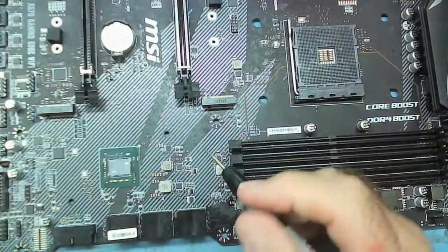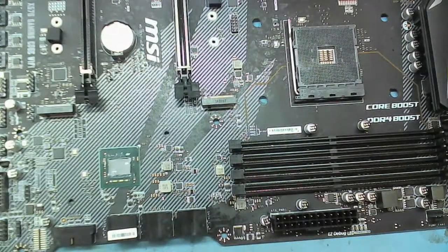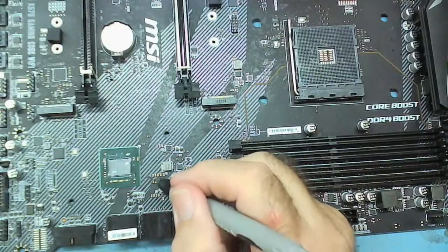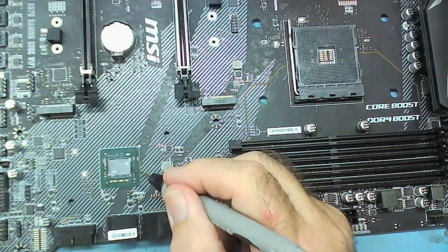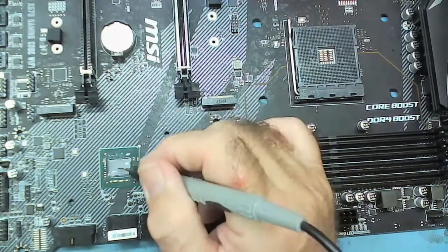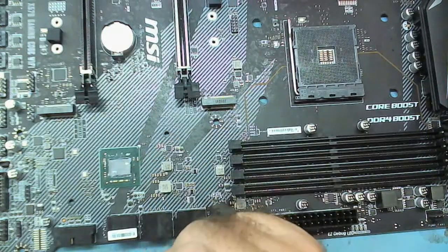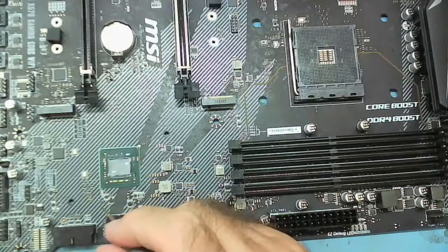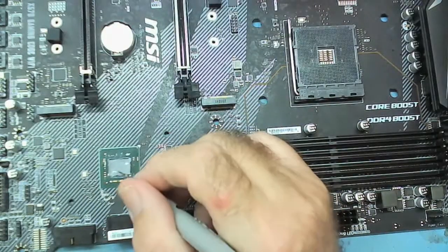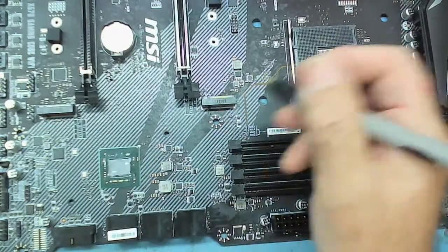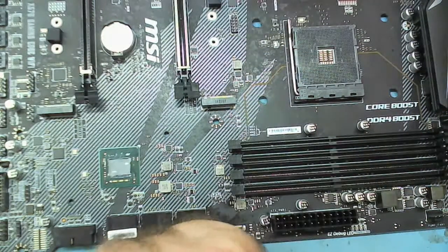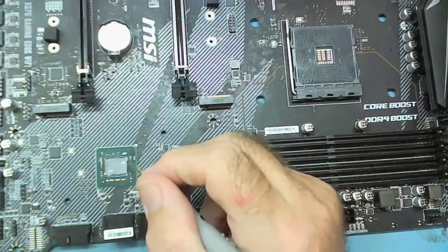So this is the board that doesn't power on, and we know as a fact that this North Bridge, or PCH, whatever you want to call it, platform control hub, I believe that stands for PCH, has only got 0.7 and 0.3 volts on it, and I said that seems strange when I first saw it. And we looked on the good one, well, say good one, the one that does power on even if it doesn't work, and that had 1.8 instead of 0.7, and it had 1 instead of 0.3.